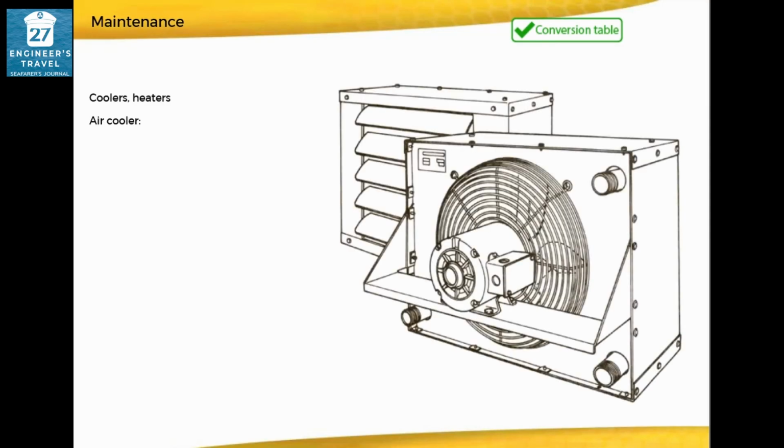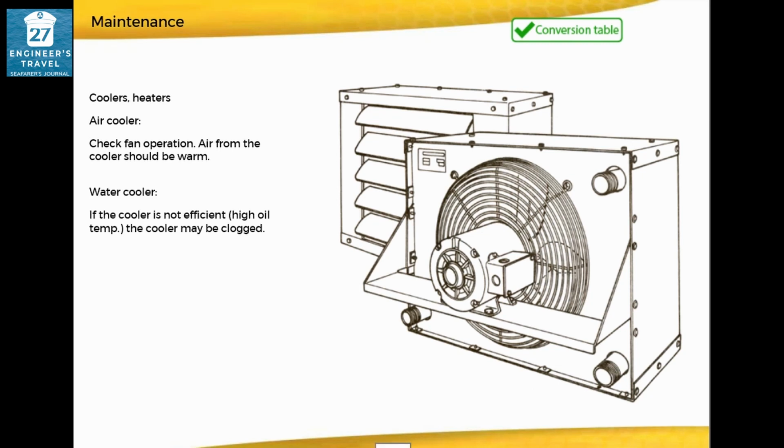Coolers, heaters. Air cooler. Check fan operation. Air from the cooler should be warm. Water cooler. If the cooler is not efficient, high oil temperature, the cooler may be clogged. Heaters. Check set point and operation.